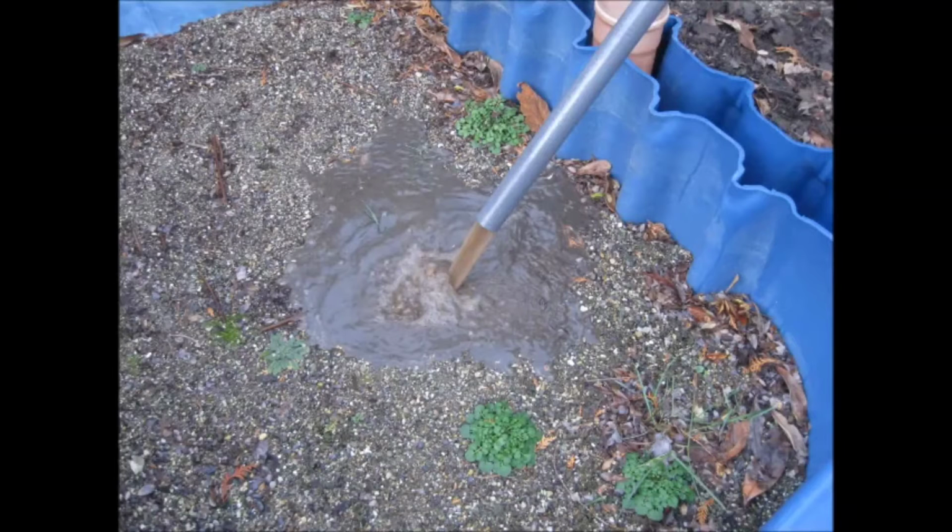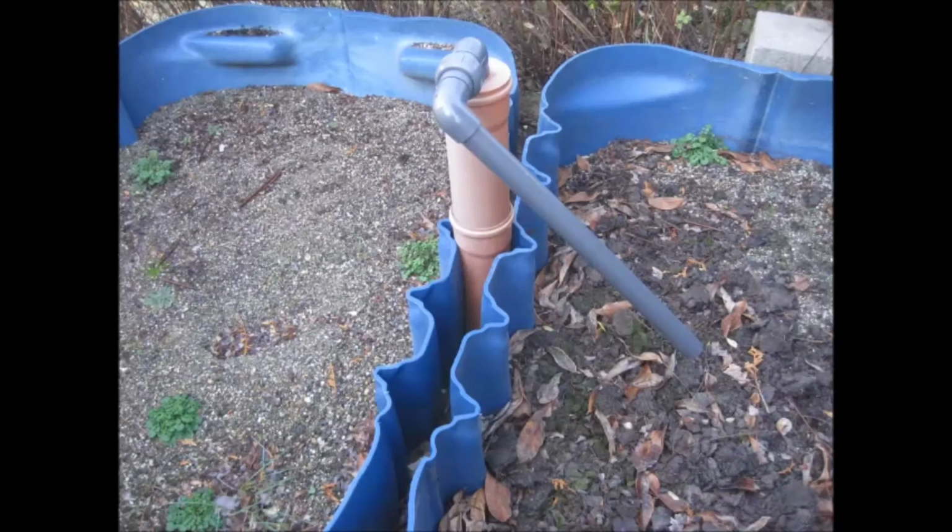This sludge is aerobically stabilized. It has no odor at all and will be sanitized by the sun radiation. The water goes through the filter and flows back into the wastewater treatment plant. After a few weeks, this sludge will be dried completely and can be taken off. It can be used as fertilizer or be disposed of as solid waste.